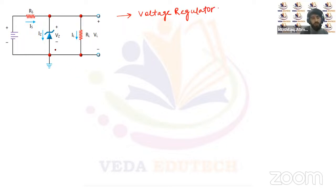It means that whatever the voltage across the Zener, if VZ is across the Zener, then the same voltage will be across this loop. Let's suppose IS is the current flowing through this circuit. This IS current will be distributed into two paths. One will be through the Zener diode, and another part of this current will be through the load resistor.